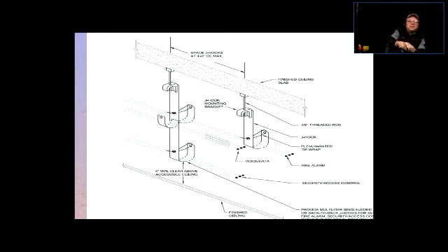The MMMF fibers are pretty much just as dangerous as asbestos fibers, because they get into you and don't come out, and they can cause cancer. So you have to make sure that the insulation that's there is not MMMF. If it is, then different procedures apply to installing or messing with that.